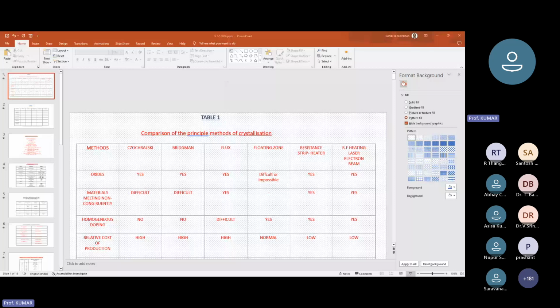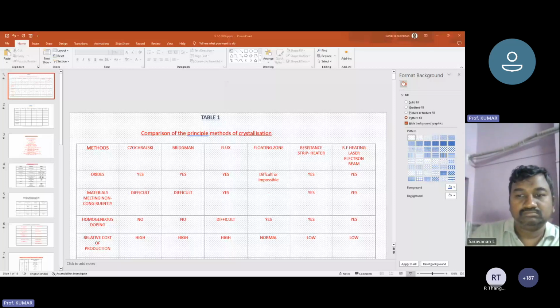With a simple tool of having an electric current flowing through a semiconductor, while you apply a magnetic field in the perpendicular direction, then in the third dimension, you can measure the corresponding Hall voltage. With that measurement, you can find out the mobility and the carrier concentration, which not only gives you the quality of the material, but also enables you to design the material for a given application.